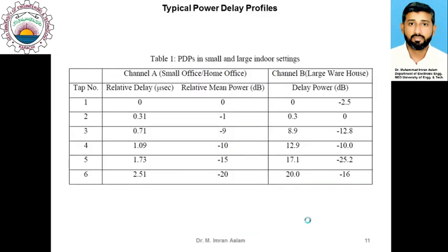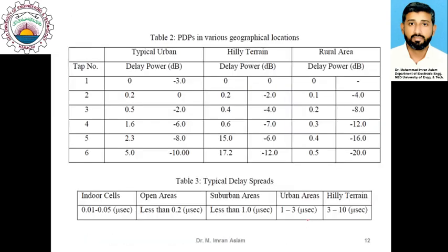So this concludes our discussion on the delay spread and the coherence bandwidth. The delay spread is one of the physical phenomena which comes from the fact that signals propagate through different paths, and the different components associated with different paths arrive at the receiver with different delays, and those different delays cause an average amount of delay spread.